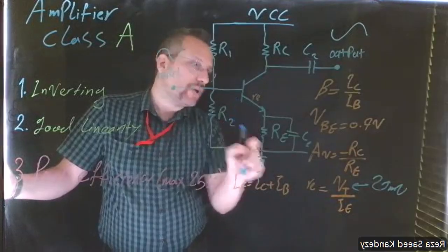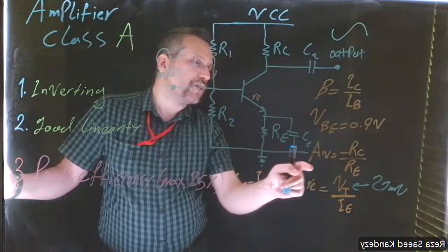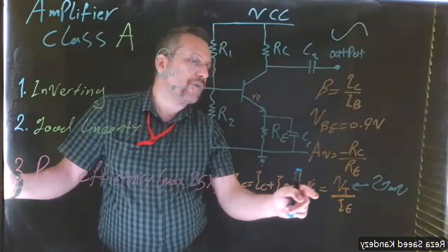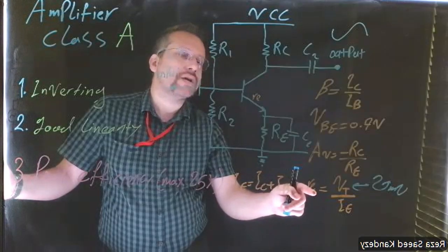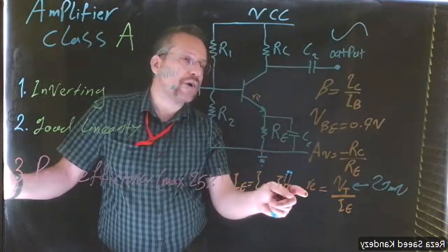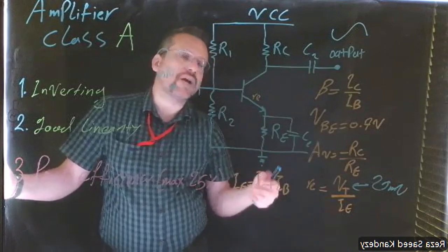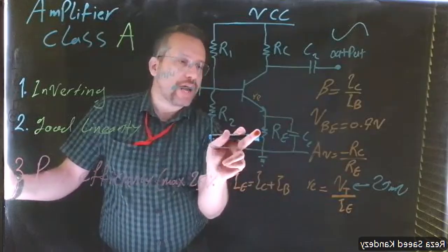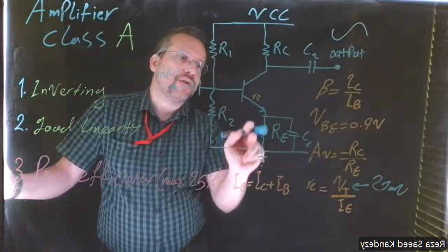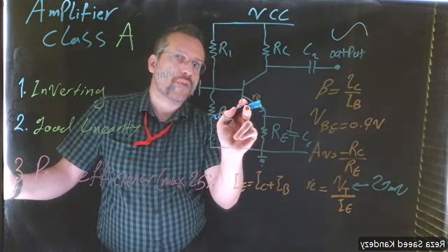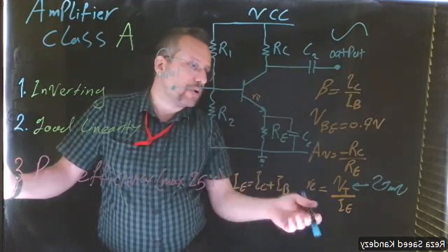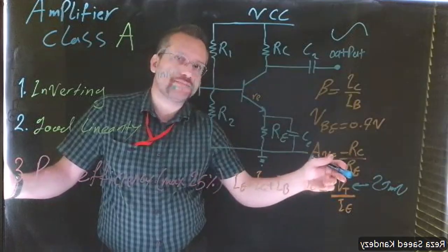Now, what we want is to dominate the resistance so that the effect of this RE is very low, and the variation in that RE would not significantly affect our result. To do that, we add this capital RE resistance on the emitter, which is much higher than this one. So it would dominate the whole resistance and cancel out this variation effect.